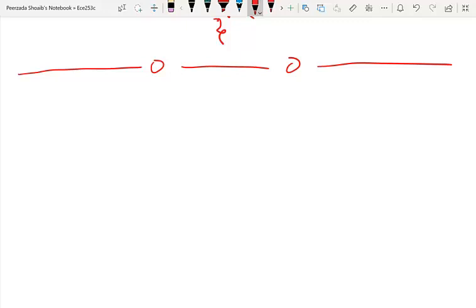One of those functions is _delay_ms. This gives delays in milliseconds. We can write any number in the brackets, for example 100. If I call this function, it's already been defined, I don't need to define it. It will actually incorporate a delay of 100 milliseconds